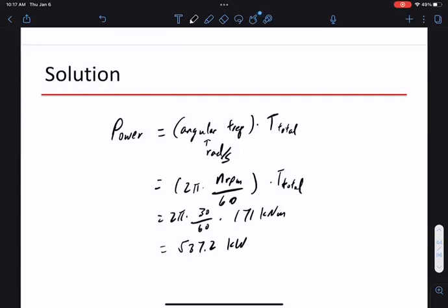Right. So 3 blades also have a benefit that the weight is fairly evenly distributed across the system. As you have 3 blades turning, at any point, the weight is actually evenly distributed. This is like the 3-phase power in AC power flow. With 2 blades, depending on the orientation of the blades, the weight distribution is very different. For example, they can be straight up and down, or they can be flat. And it creates very different weight profiles on the tower and the blade.